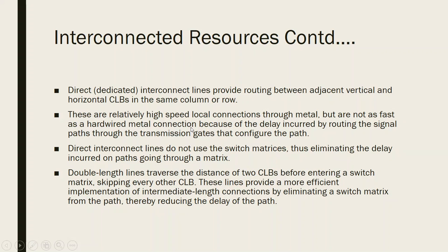Direct interconnect lines do not use the switch matrices, so they eliminate the delay because of the switch matrix. However, it is still slower than a hardwired metal connection.